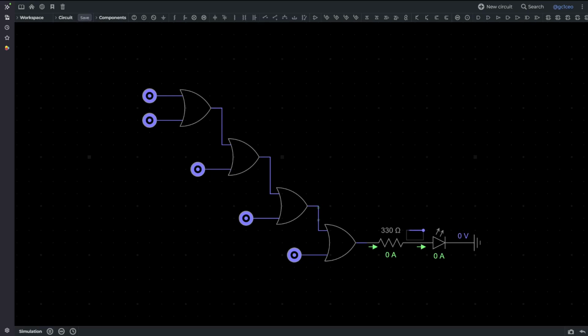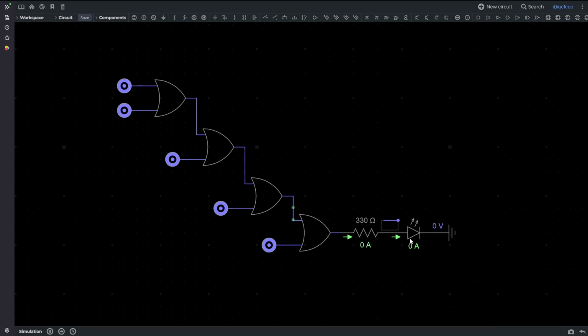All right, now I can't produce the IC for logic gates in every circuit, but I can show you with logic symbols how the five input OR gate I was talking about might work. So you've got all these, and the light will light up if any of these conditions are true because this is an OR gate. So that lights up, that lights up. It's not going to matter if they're all lit up, as long as one of these is true.